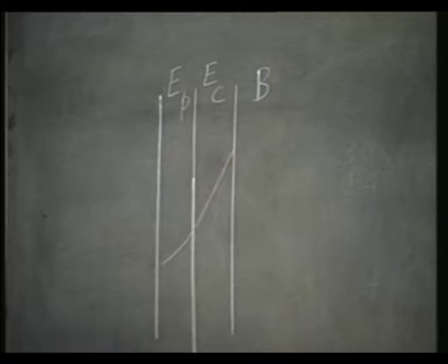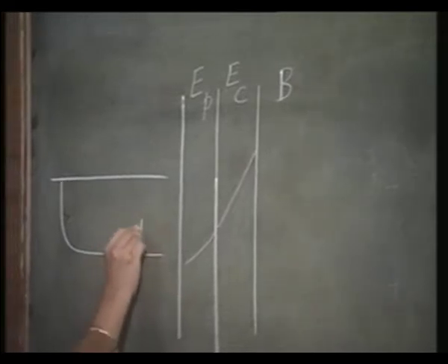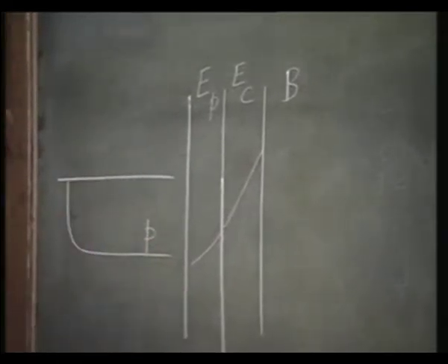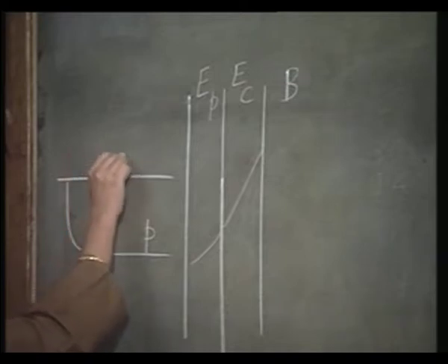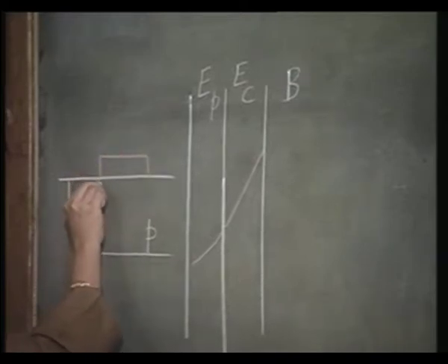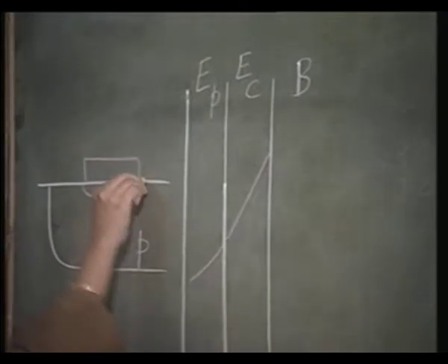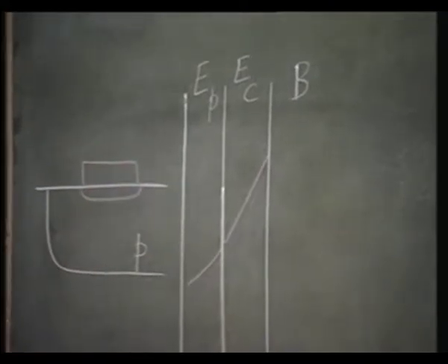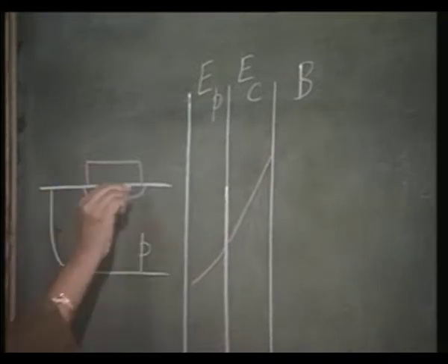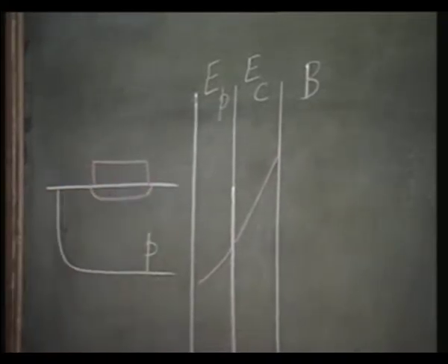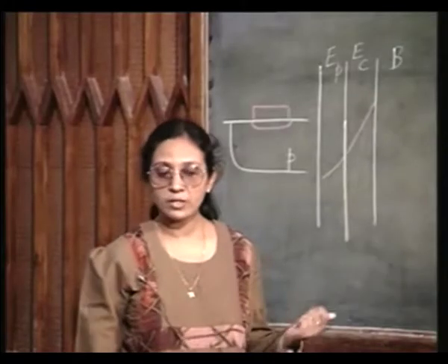What I am trying to say is this, I have the P plus region here for the base, and I have deposited a poly here. So the sidewall capacitance is only determined by this region, which is very shallow, but the entire region is working as my emitter, and therefore, the slope of this curve does not have to be very steep, it does not affect the gain of the transistor.